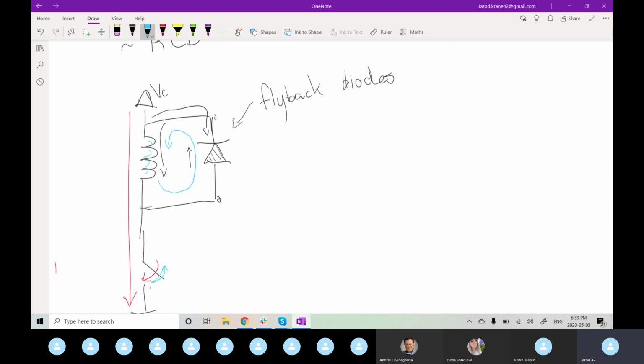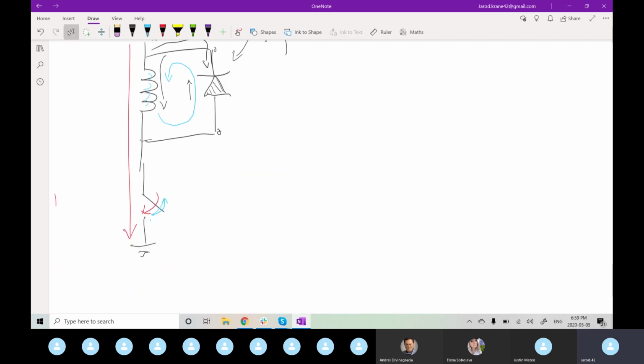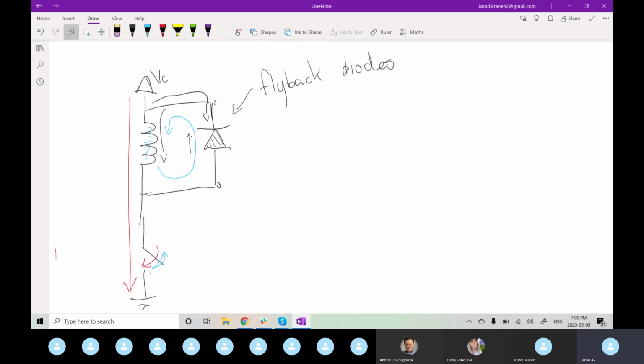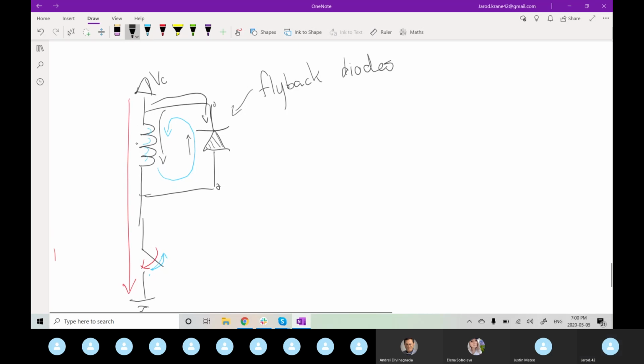Doing this allows the energy in your system to be dissipated, so the coil actually turns off faster. Because if we were to assume this is an electromagnet or even a relay, and we don't have a diode, or we don't have any snubber, there's still going to be current.